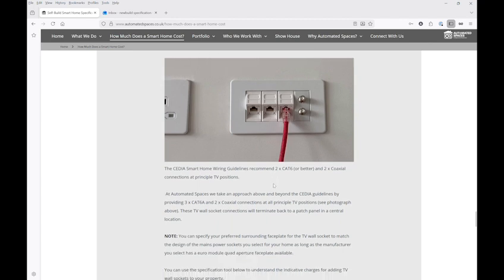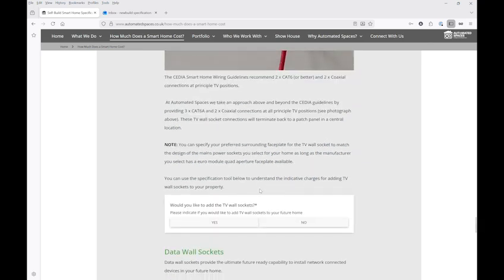So we mentioned here we go into the wall sockets for the TV points. Here we provide 3 data points now. We're seeing, with the proliferation of smart devices and streaming devices and things being attached to TVs to do different capabilities, from Sky boxes through to various other streaming devices, it's always prudent, we feel, to have additional access points, and where possible, obviously, try and wire these connections to the network rather than relying on Wi-Fi.